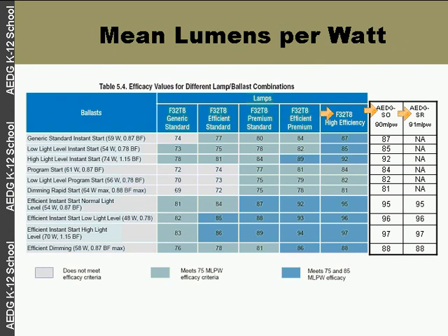In the small retail one, you can see that there's a series of NAs, so it wasn't actually available to use some of those technologies, and what you're seeing is that on the far left-hand column are ballast types, and then we have in the columns different lamp types. So the reason why it says NA is that those are not what we consider high-performance electronic ballasts. Only the bottom 4 are truly considered high-performance electronic ballasts.